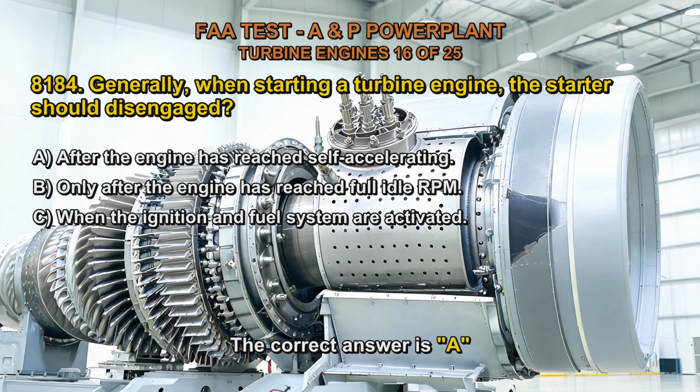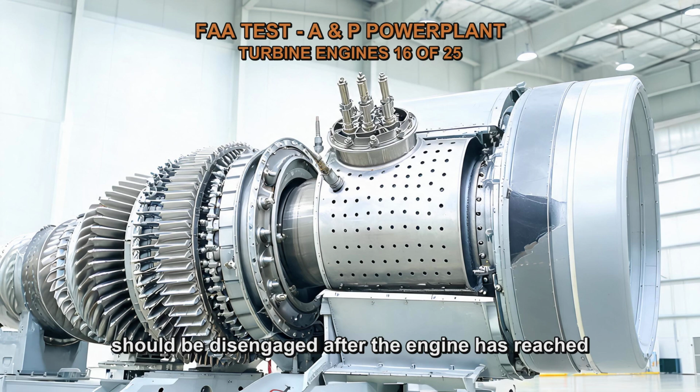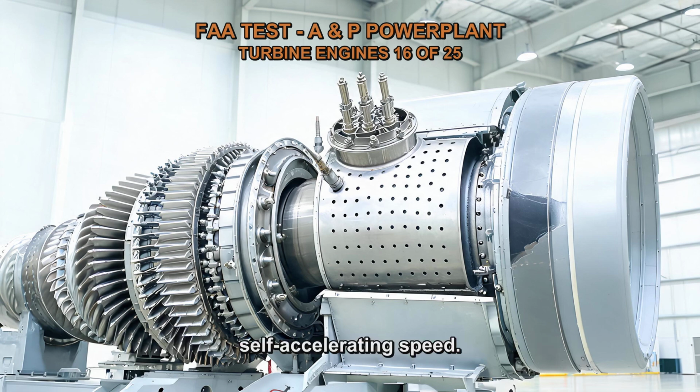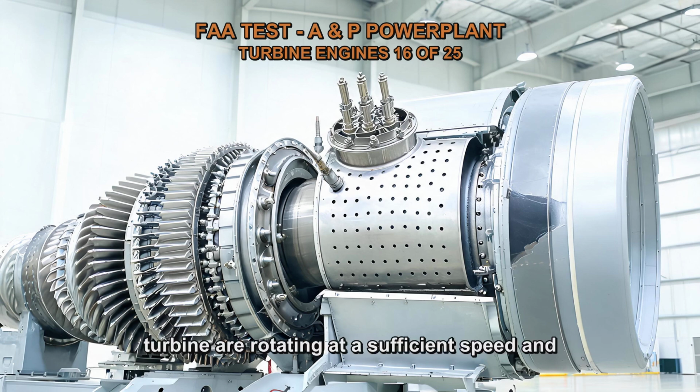The correct answer is A. Generally, when starting a turbine engine, the starter should be disengaged after the engine has reached self-accelerating speed. The self-accelerating speed is the point at which the engine is able to sustain its own operation without the assistance of the starter. This typically occurs when the engine's compressor and turbine are rotating at a sufficient speed and airflow through the engine is established.